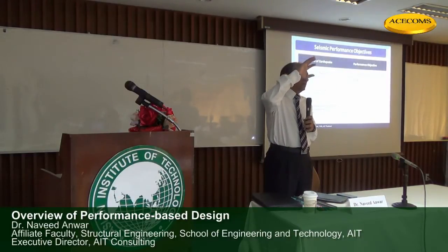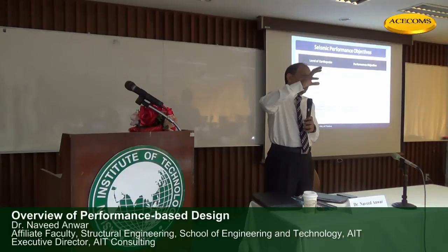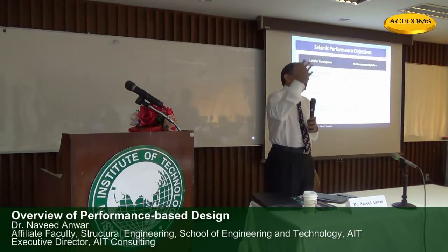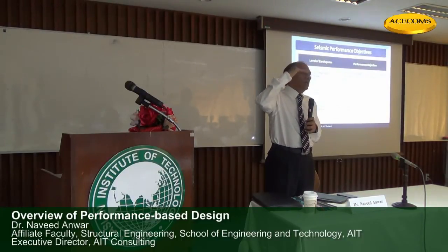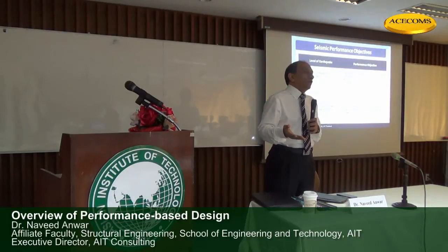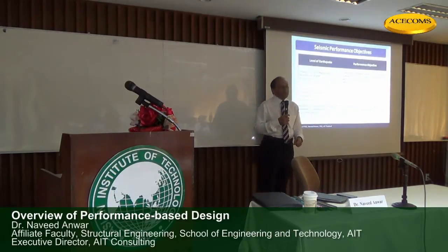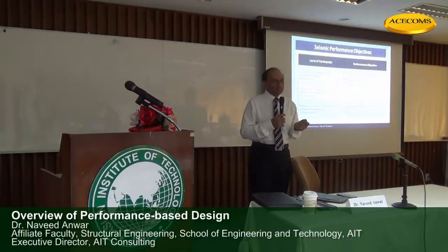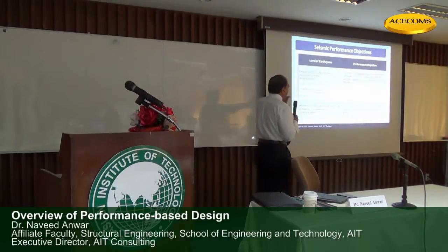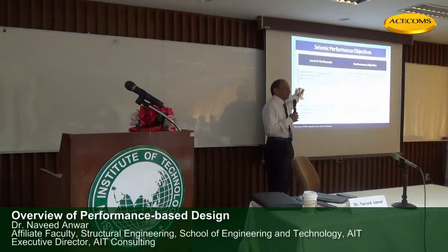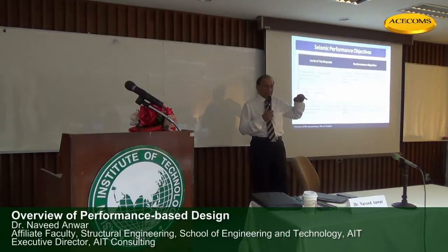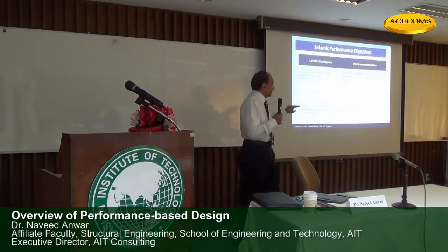Basically, it assumes that the force coming to the structure is not the one that we can design for. So we design for a value much less than that, 1/4, 1/6, sometimes 1/10 of that. And that reduction we are expecting to happen because of the damage and energy dissipation and other factors. So which means that we are expecting that with this earthquake that will come once in a lifetime maybe, the structure will be damaged, but not too much. What is too much? Okay, that needs to be defined.